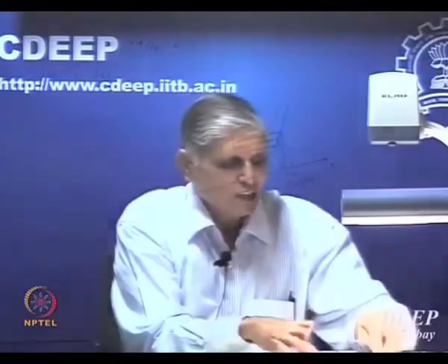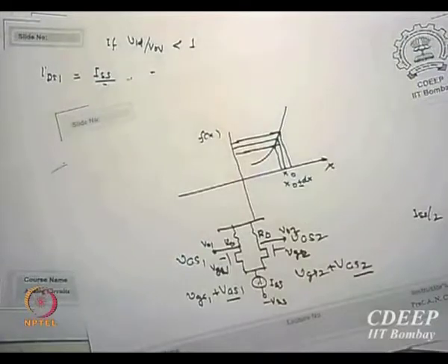Because for an amplifier, common source, common emitter, any kind of amplifier, what is the thing we always say? Gain is constant. That is, gm is constant, and to do this we must have linearity. To make it linear, the condition must be met. Is that clear to you? So this is not really the solving part, or something we need to do. This is just to prove my point that you cannot have large signals with linear zones. As the first slide shows, if you swing your signal from here to here, you cannot say they are linear.